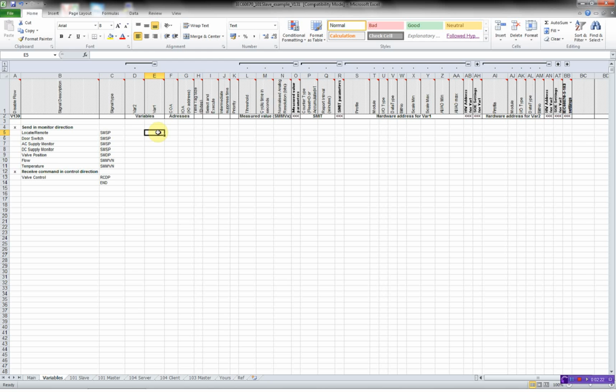Here I use the naming convention digital input, module 0, and bit 0, and so on. In this double point information, I'm actually using two variables. I can choose whether to define the second variable by myself, or the generator will automatically take the di0_4 and then an _2 for the second variable.